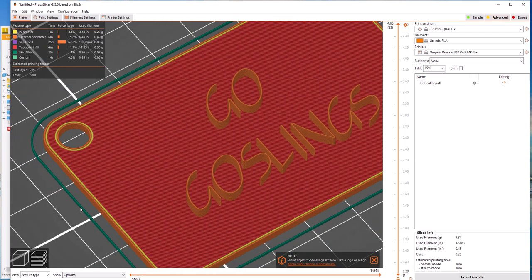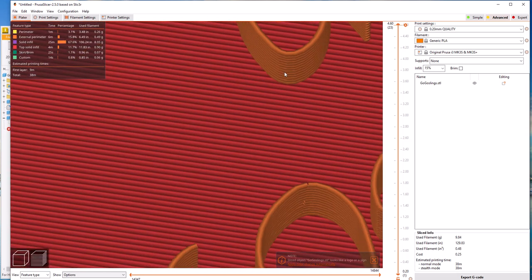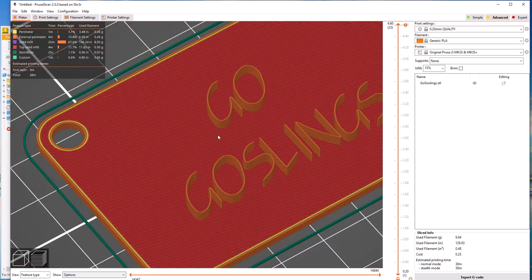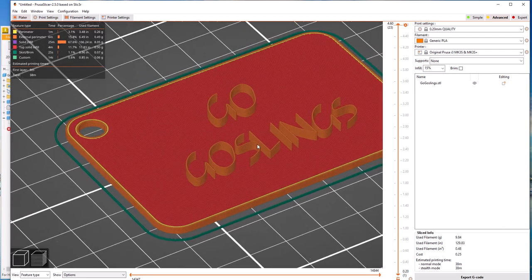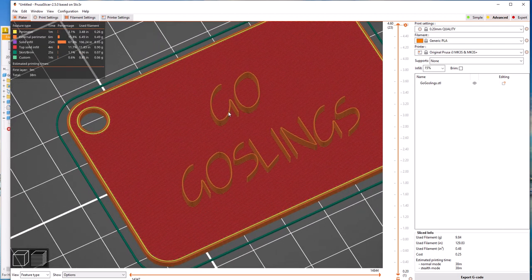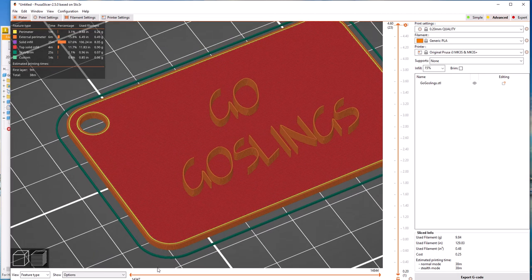so it's pretty weak. Plus it's way higher than it needs to be. I mean, we're like 15 layers tall or something here, 10 layers tall of just the letters. Do we really need it to be that tall for what we're doing? So sometimes the choice of font can make your part print successful or unsuccessful. And then just the design, does it really need to be that tall of lettering?